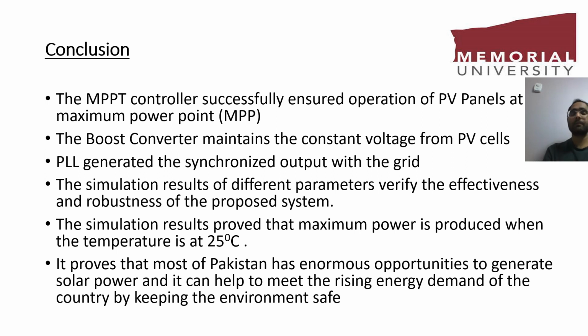The boost converter does its job and ensures the consistent output power from the PV cells, and the PLL, phase lock loop, ensured that the power which is fed to the grid station is synchronized with the grid station.